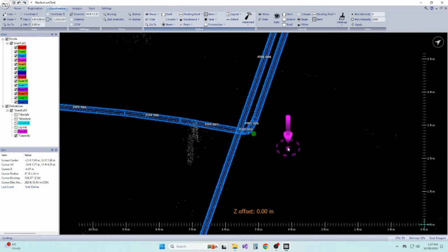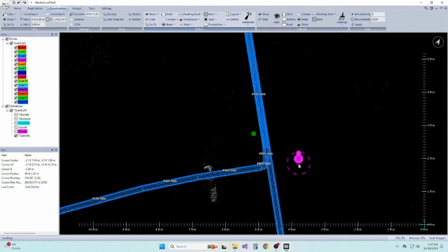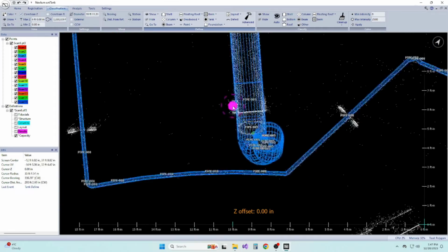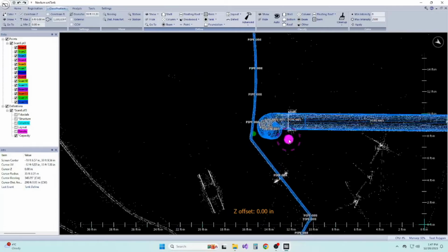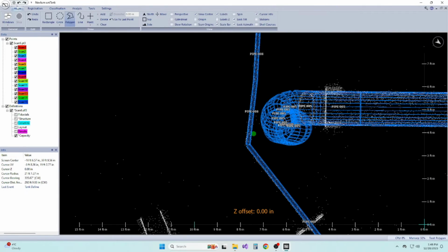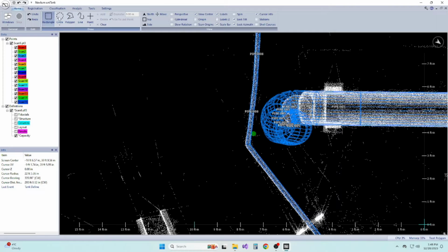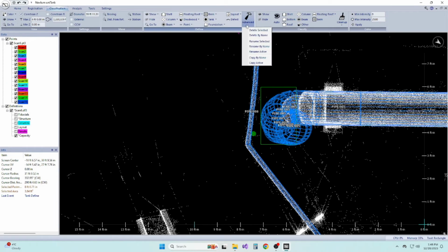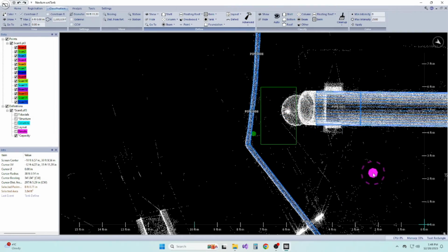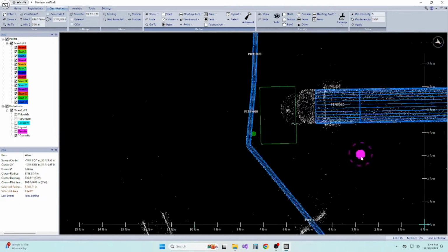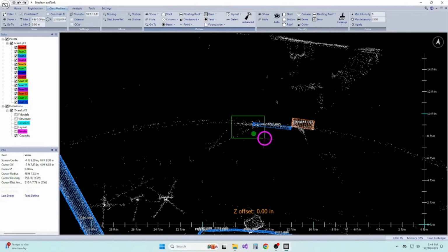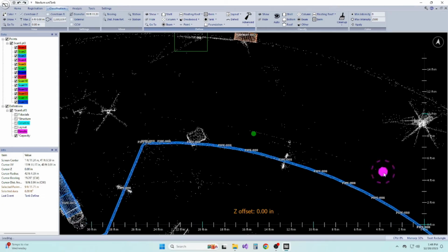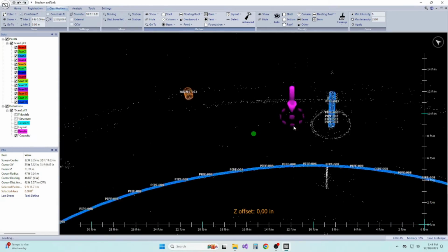At this point, I want to draw your attention to the colors of the Deadwood. To make it simple to recognize, orange Deadwood are items that add volume on the outside of the tank, such as manways and sumps. Blue Deadwood are items that subtract volume inside of the tank, such as columns, pipes, and nozzles. Outside Deadwood is created as solid items because their entire volume contributes to the overall volume. Inside Deadwood is created as hollow items because only the pipe thickness usually reduces the overall volume.